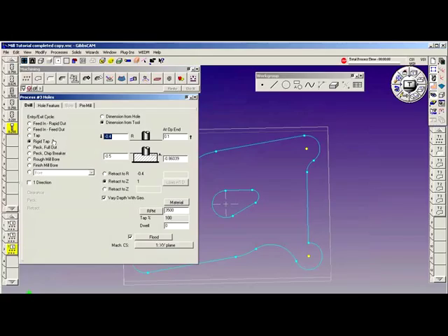And you notice that rigid tap is already selected for us. That is based on the tool definition. We're going to rigid tap. We're going to go down to -0.2. The stock begins at -0.5. And we're going to take the point down to -0.75. Gives us 50 thousandths to the bottom of the hole.